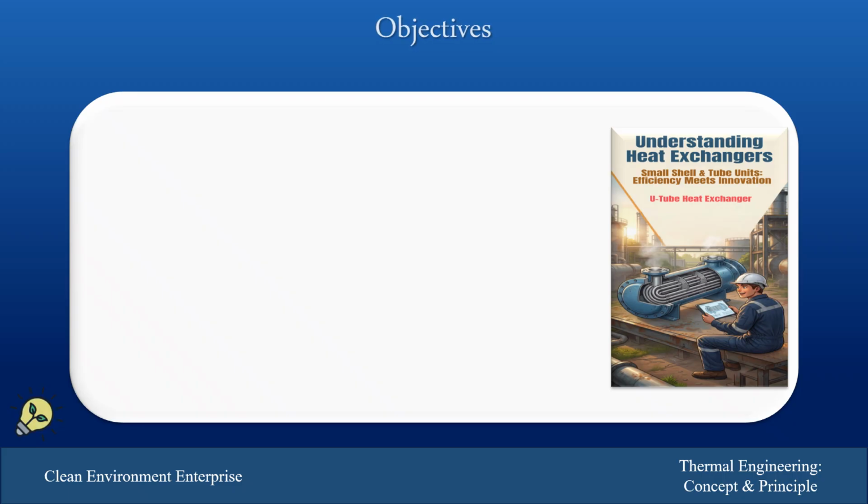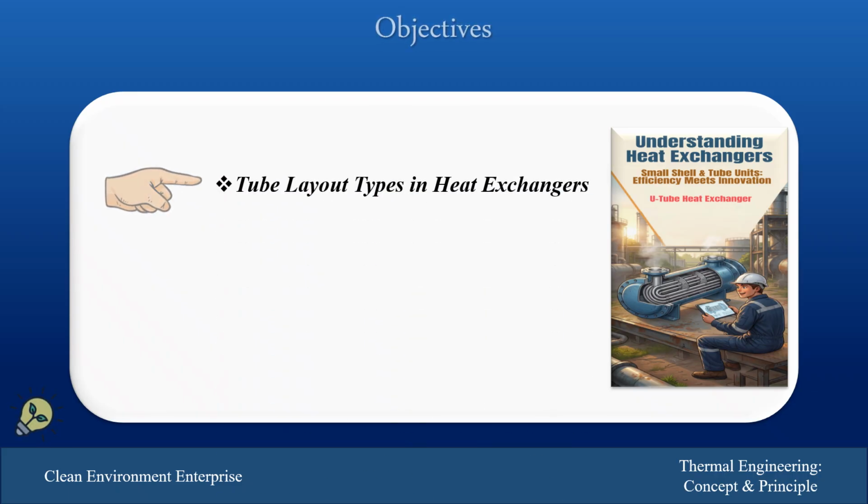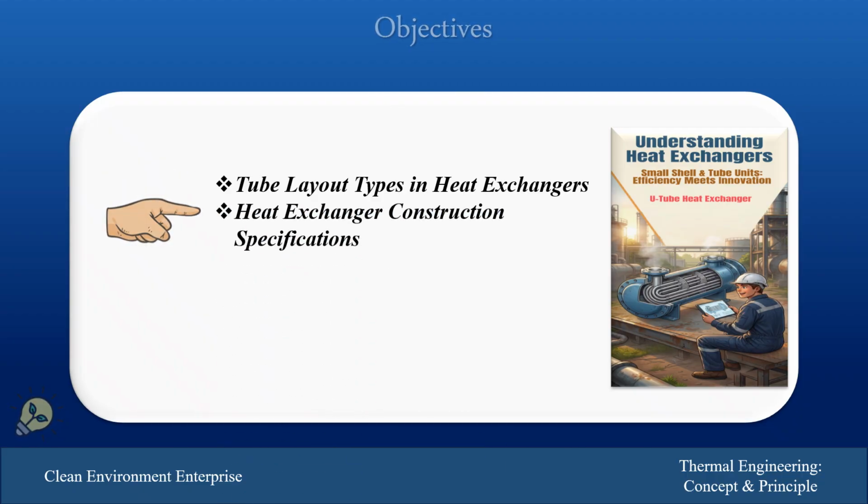The objectives of our episode can be summarized as tube layout types in heat exchangers and how these tubes can be arranged, and heat exchanger construction specifications related to other physical parameters of the heat exchanger such as the length, the shell diameter, baffle cut, baffle spacing, and many other parameters.